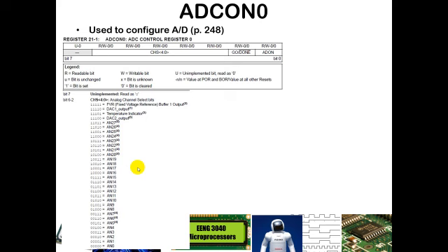So it is important to note that with our microcontroller, even though we have 28 different analog inputs, we will cycle through and only be able to digitize a single analog input at one time. Now we can do this very quickly. So if you are sampling multiple sensor inputs, as we will later in the course when we get into interfacing with a 3-axis accelerometer, what you will have to do is collect data from one channel and then reset the channel that you're collecting data from, capture that channel, convert it into digital format, capture that data, and then convert to the other channel and go on until you have captured all of the channels.